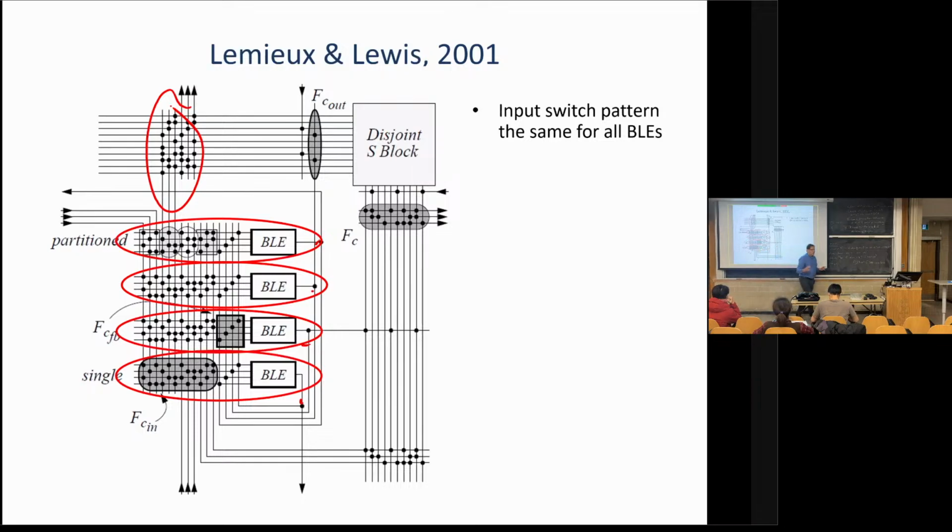But if they say the cluster can use 30 inputs, but I'm going to build 34, I'm not going to tell it I have 34, right? The extra 4 are my secret. It becomes much less likely that you'll get blocked. It's a lot easier to get 30 signals through something that has a peak routability of 34 than it is to get 30 signals through something that has a peak routability of 30. So they could have equivalently done this, probably, by not increasing the number of inputs, but just telling the cluster to use fewer. That probably also would have worked okay.